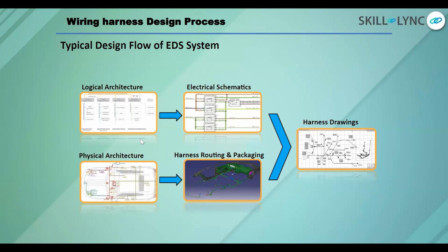And then further, from the back side, you can see your tailgate, tailgate light and other components, correct? So based on this physical architecture data, you are going to develop something called the harness routing, wherein you are going to place the components and then develop the routing with respect to all the body structures, so that the wires are intact in the system. So that's what we generally do with wiring harness, or that's what we understand by packaging. What we are doing in packaging is packing the systems properly so that everything is put up in a neat and tight manner, correct?